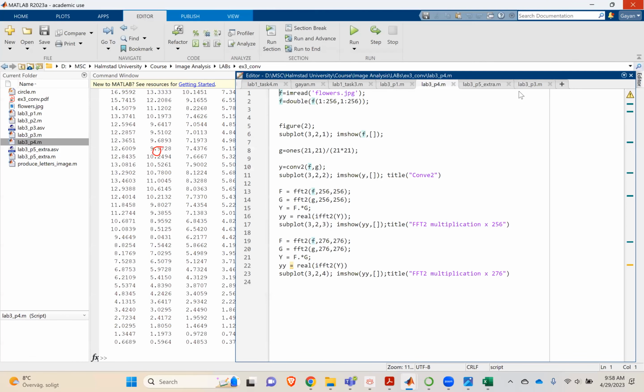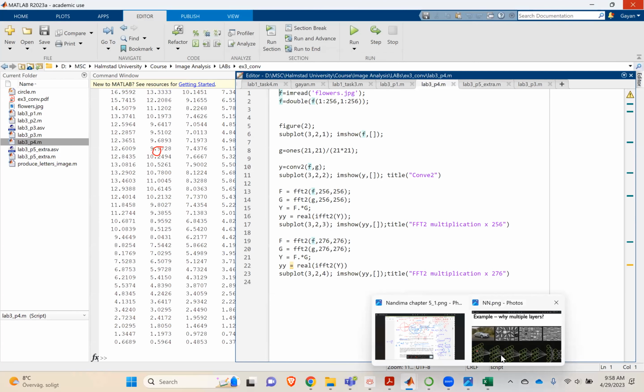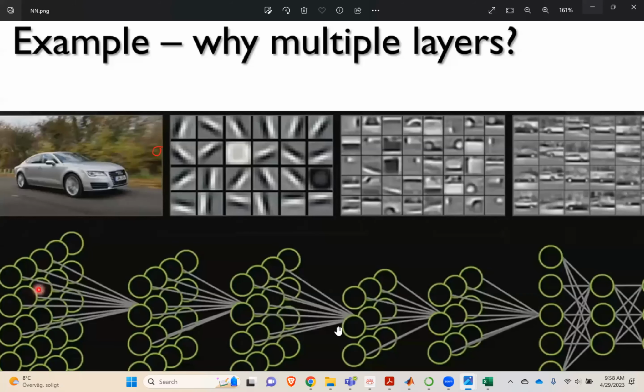So what we can do is for those kinds of scenarios, if the original image has noise, we cannot match it. So it's very sensitive to noise. As a solution, we can just apply a low pass Gaussian filter, and it can reduce the noise. Or if this is your real scenario and you are getting some noise, then you can apply a low pass filter, so it will fix your problem.